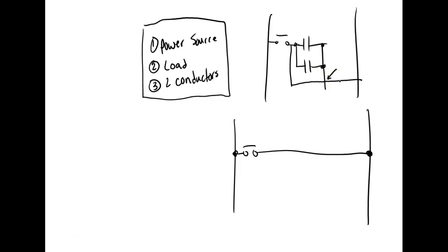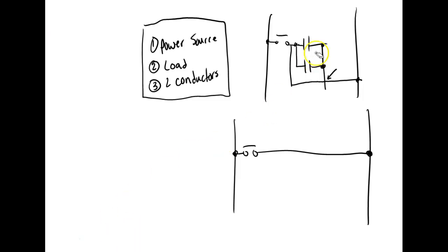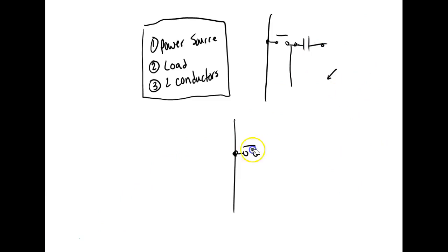Unfortunately, when they came out with the PLC programs where you draw ladder logic, what don't they put? They don't put the dots. We cross lines and those things also, but they don't put dots to indicate a connection or not a connection, which on a PLC gets kind of confusing sometimes.